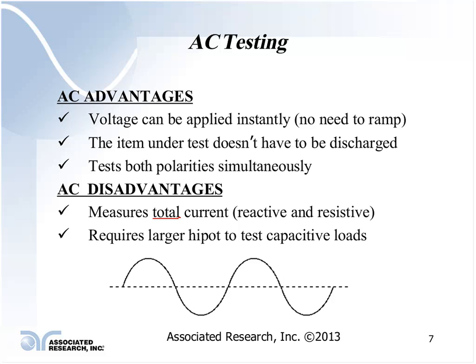If I'm more worried about it from an insulation standpoint, then I would be more interested in what the current is due to the resistive element of the product. There are Hipot testers that can measure both the real and total current. They are a little bit more expensive. Having that capability of monitoring both of these requires some special circuitry.